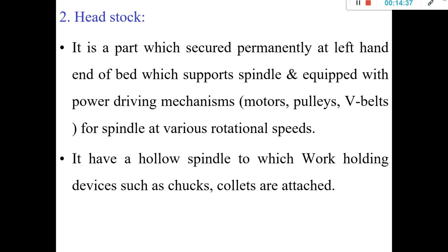Now the headstock. It is a part which is secured permanently at the left hand end of the bed, and supports the spindle and is equipped with power driving mechanisms such as motor, pulleys, V-belt, etc. for the spindle at various speeds of rotation.